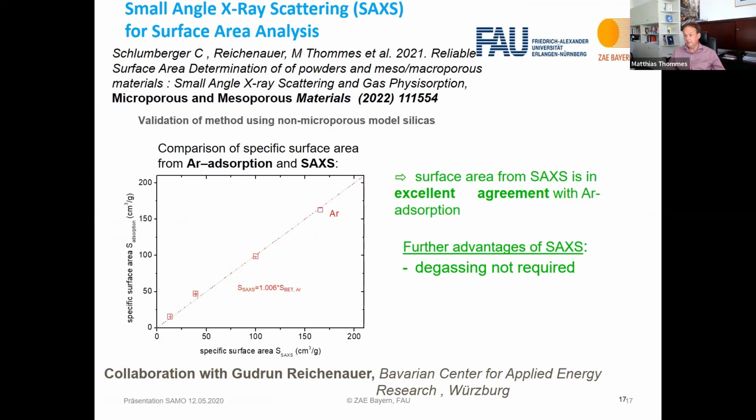When you look at the very accurate calorimetric measurements done, for instance, in the Rouquerol lab 20 or 30 years ago, you could demonstrate that when you have a material without micropores and without narrow mesopores, on the order of 2 to 4 nanometers, the BET theory can essentially be applied quantitatively, and you could consider this area a true, probe-accessible area.